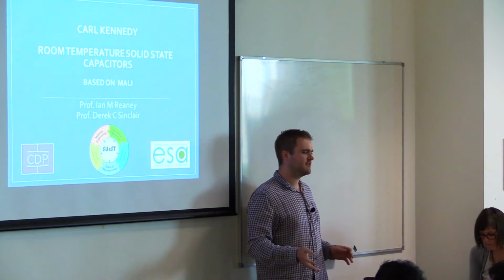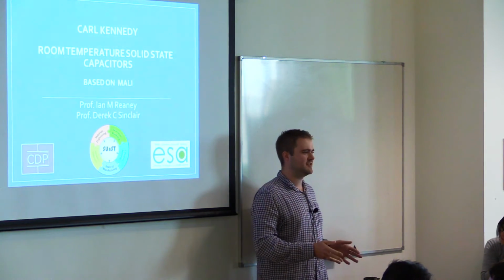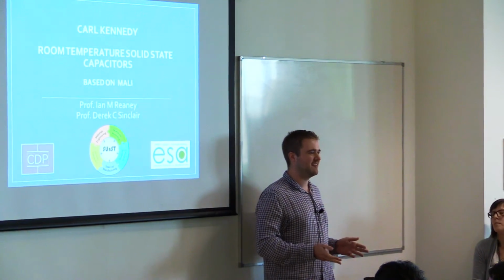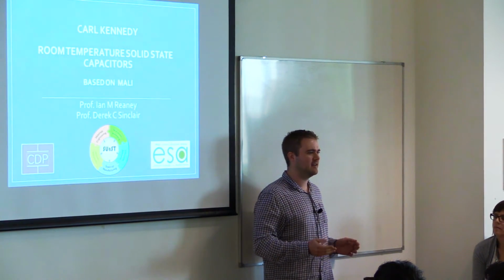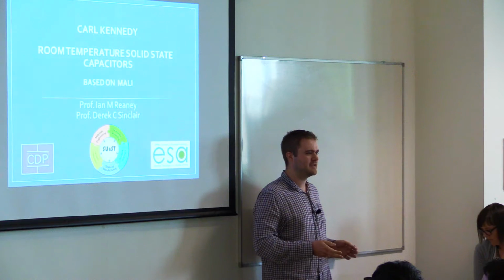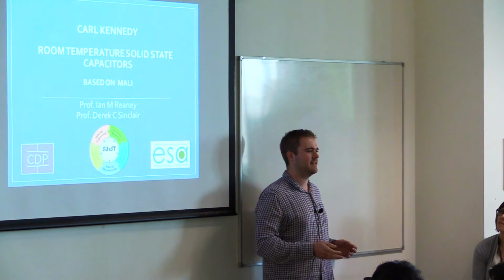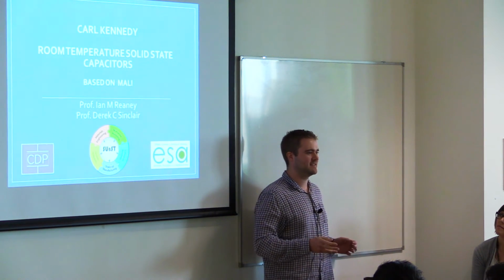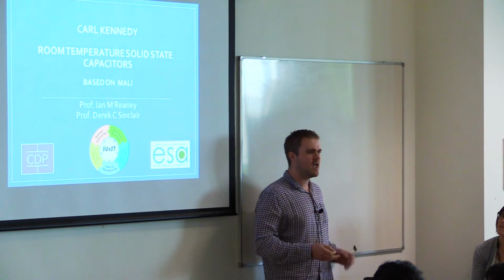So on shorter urban feeders, that might not be so much an issue. We might not need the storage even to provide voltage support. On longer feeders with a lot of customers, we start to see problems at fairly low penetrations with voltage imbalances and steady state voltage issues.